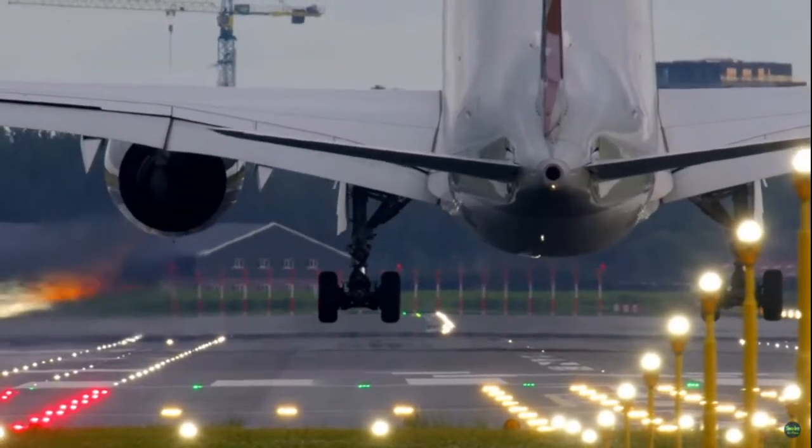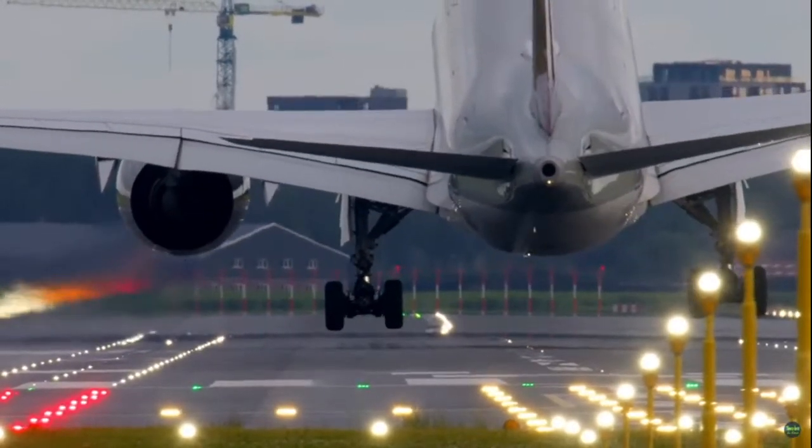If you do that, you might be flying at 120 to 150 knots when you touch down compared to 250 knots, which is likely what happened with this flight. That's that much more energy. Remember, the kinetic energy is 1/2 mv squared. So if you increase the speed, it's the factor of the square of that speed. That's a lot of energy at play, and it all went careening into that embankment. So if we had the flaps deployed, that would have helped.